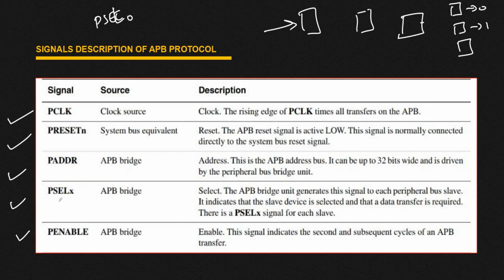After that we have PENABLE. Just keep this in mind: if your PSEL is asserted, then on the next cycle it is mandatory that your PENABLE should be high.